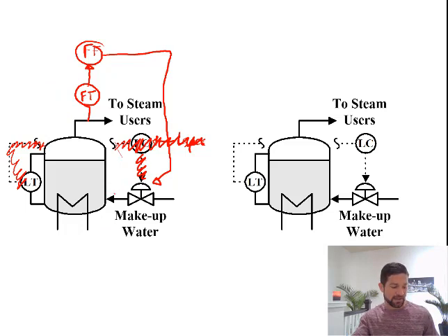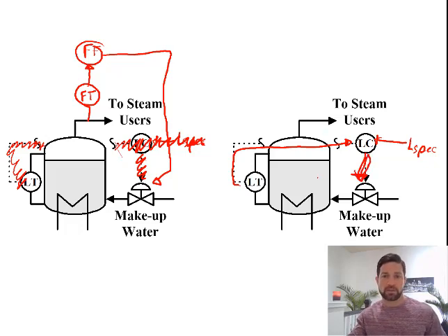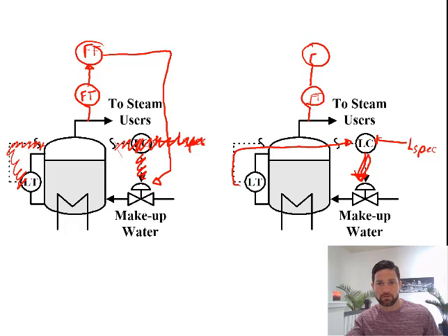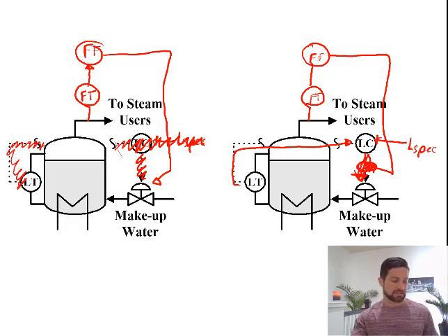All right, if we want to incorporate this now with feedback and feed forward control, we have our primary control loop, our feedback control loop shown here. So we have a specified level, we take a measurement of the level, and this changes the valve. Okay, so feedback or feed forward, we do the same thing as we did over on the other side. We have our feed forward controller, and both of these signals would be combined together to change the control to the system.